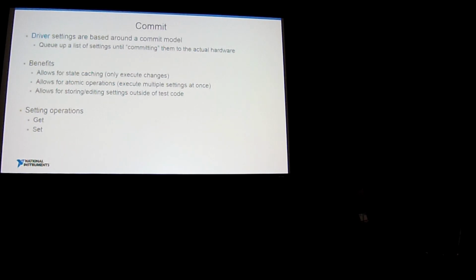The other one is that it allows for atomic operations. Some drivers are really optimal, and you bought it because you want to take advantage of that optimization. So you say, I'm going to set 50 settings right now in one operation. I want to send it all at once, and the driver knows how to do that really fast. Maybe you put it in a string, you send it all at once. So if we do caching or commits on known cycles in your code, you can queue up 50 commands, send it to your hardware, and then your driver can send them all at once. It can be very optimal in how it handles those changes.